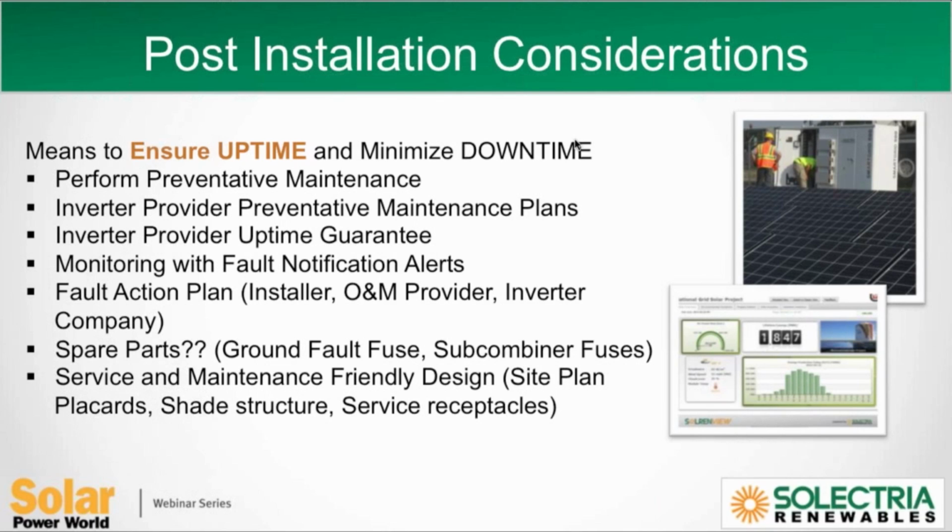Even though the inverter doesn't have any moving parts, any inverter is going to vibrate slightly, and there's expansion and contraction in connections driven by temperature changes. So you want to have a good preventative maintenance plan, and your inverter provider will be able to provide preventative maintenance guidelines for their product. If you'd rather have the inverter experts cover it, there's the possibility of a preventative maintenance plan from the inverter company. There are extended warranty options and uptime guarantee options.